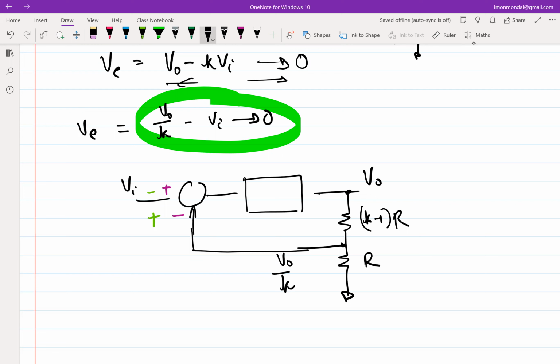And we said that this stuff inside the loop, this forward path, essentially has to be an integrator. So we say that this is omega u over s, or omega u integrated over t. And then we take a call, right? Initially, we don't know whether these signs have to be plus on the Vi side or plus on the Vo side.